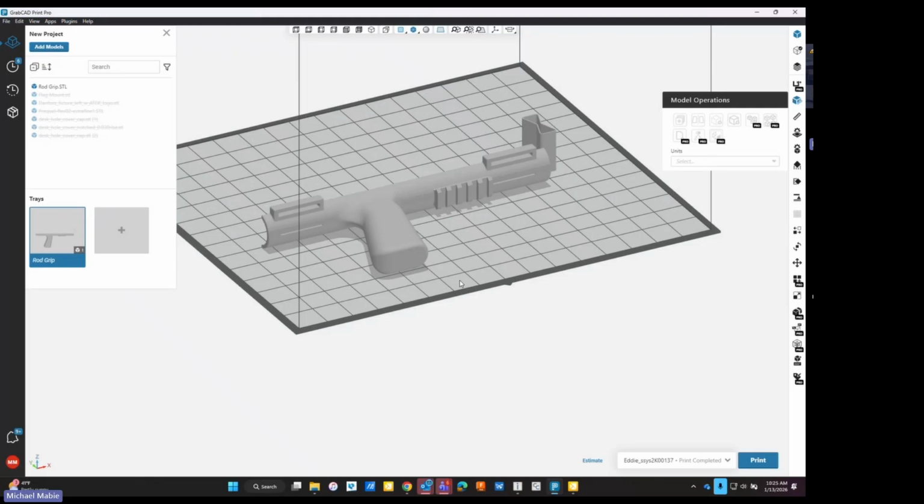As far as running on the F series, the nylon CF10 and the Duran, Stratasys has foil bags. I've seen some customers use a Rubbermaid container with desiccant packs in it to try to maintain the dryness. Anything you can do to help prevent that material from absorbing moisture before you run it in the machine is going to result in a much better, cleaner looking part.